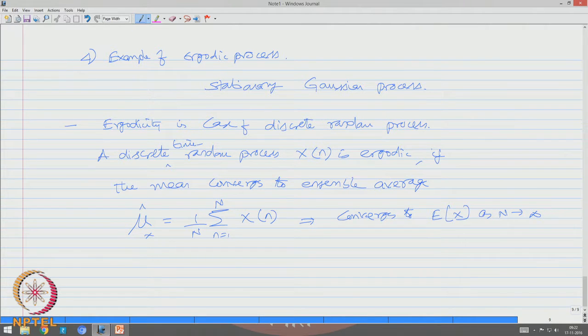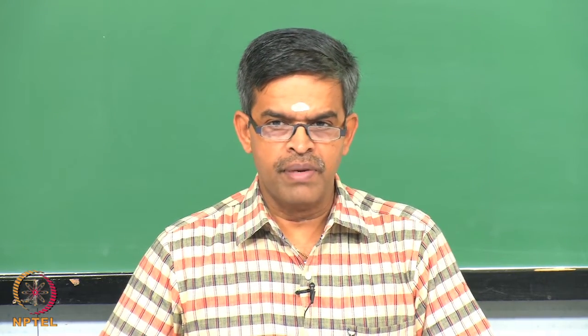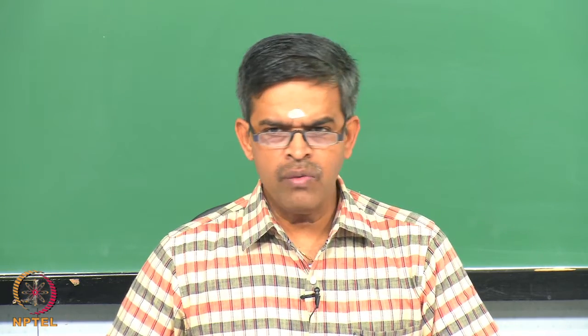So, friends, we have understood that the input forces defined in terms of spectrum has certain parameters based on which the values are estimated. To estimate these spectrum, we need parameters, correlation characteristics. We generally assume this to be ergodic and stationary process. Now, we understood what is ergodicity, and now we look further into what we mean by response spectrum and how we actually bridge the response spectrum to the input force spectrum to actually get the response.